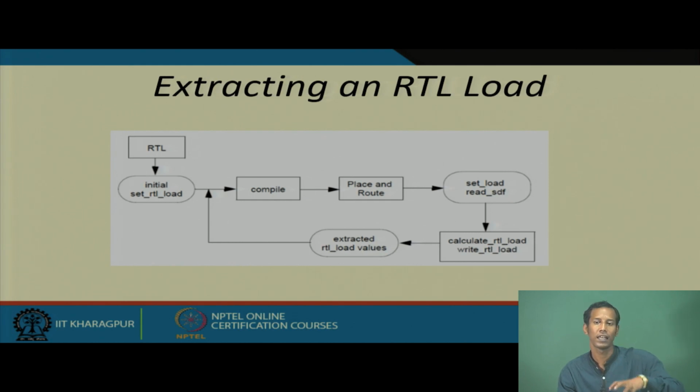All the C and R values you have to extract, and then they will be back annotated and calculated depending on whatever RTL code you have written. So, it checks the timing. Suppose you have set your clock period requirement as 5 nanoseconds. It performs all these steps, all the delay information is calculated, and it corresponds to your required time. If you have said 5 nanoseconds, that is your required time.